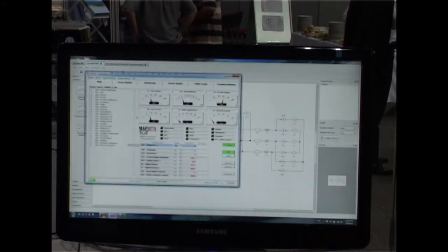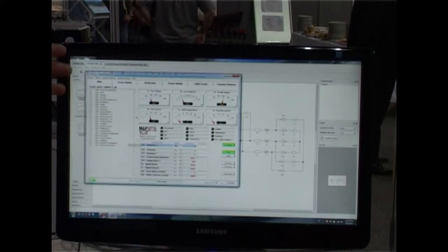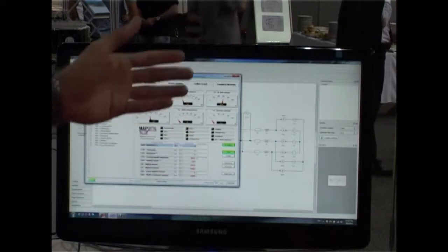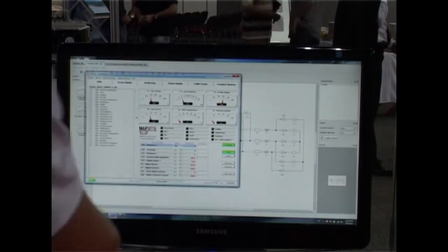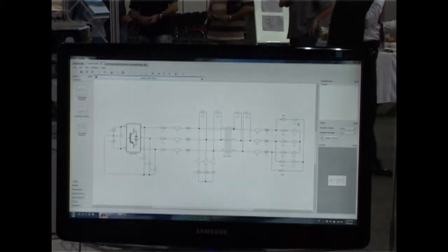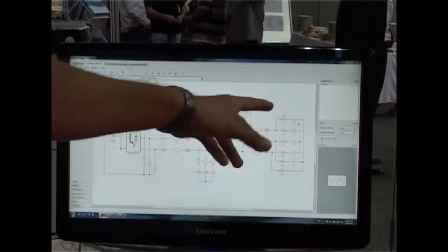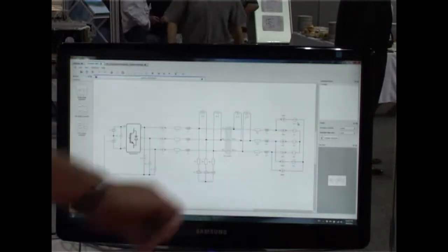In this window, we are looking at the control panel for this multi-purpose controller. Here we can set different parameters. We have signal readings from the controller, and we can turn on and off harmonic compensation used by this filter. Also, another important point in the model: the load is modeled by means of current sources connected in parallel with the grid.